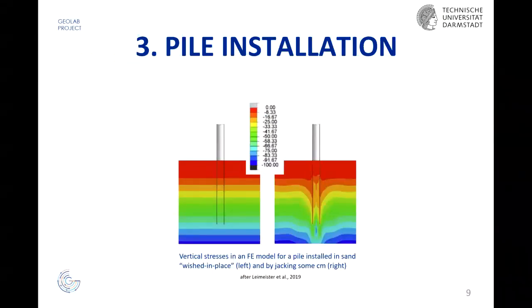Next thing for us, which is important, and since we target our training and this workshop so that it's all related to piles, of course we need to consider how our pile finally comes to the soil model. And here you have a small presentation. On the left-hand side is how you do it in several numerical studies. So your pile is wished in place and the soil conditions around it are not disturbed at all by the pile in the initial situation.